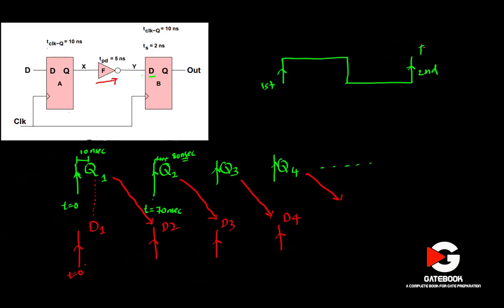Just focus on D2. So the input for D at this moment is actually coming from this Q, correct? For that, first Q1 has to be prepared, and that should go through this inverter. Then after that, that should be connected to D. Alright. Now if you start noticing from here, at the first clock cycle that Q is not available. So when is it going to be available?